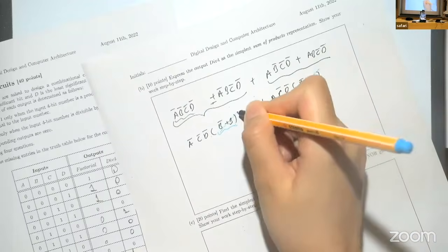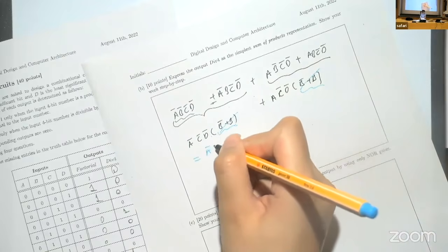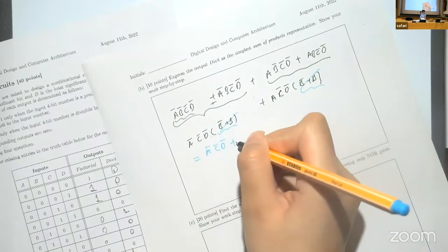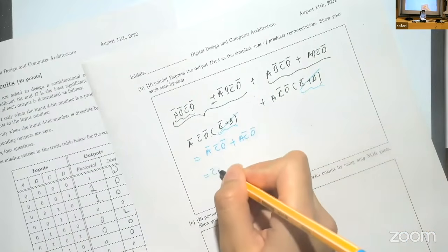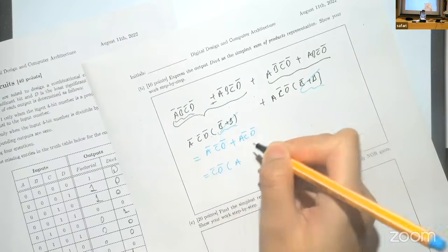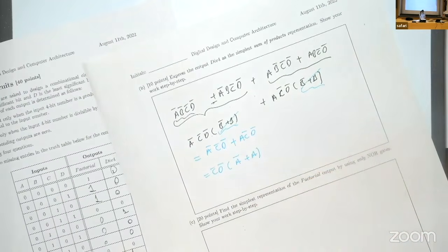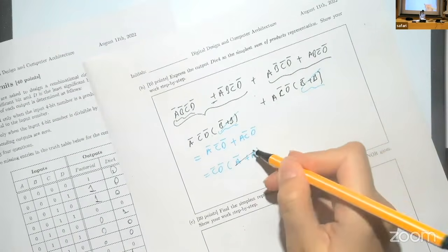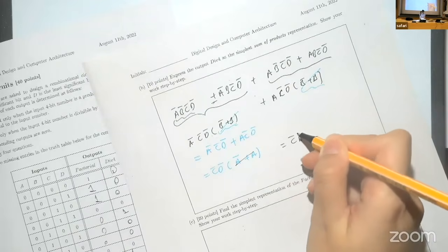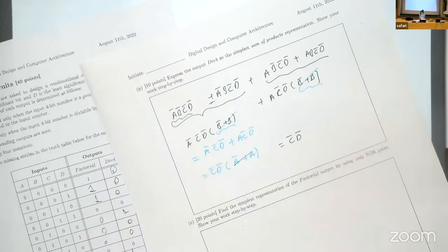So these are done. And then the D4 is simplified to A naught, C naught, D naught, or A, C naught, D naught. And we can get this into C naught, D naught parentheses by ORing A naught and A. And in the same logic, this is also 1, A or A naught, because either one of them has to be 1, and then the result is C naught and D naught for this solution.